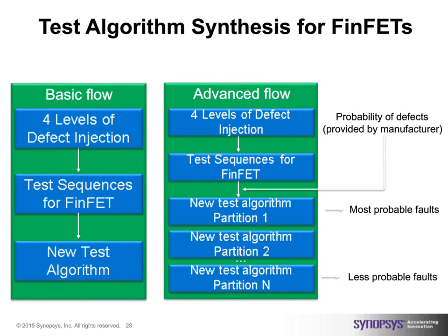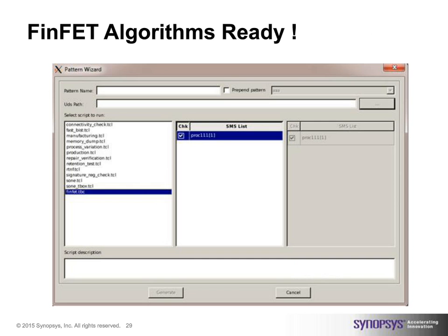In the STAR Memory System, we have already implemented this looking at the different providers of FinFET, and gladly, we saw wide commonality between them. Even though the bit cells are different from each other, the behavior of those bit cells by different foundries was not drastically different from each other, were quite similar, so that was a nice thing for us to notice. And therefore, we have augmented our solution with the FinFET algorithms in them.